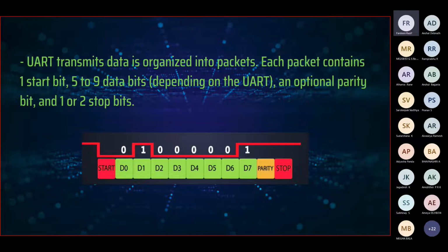So by that logic, each data bit will take 1 divided by the baud rate. That was what I was hoping for. So initially the data line goes from high to low, to show that the data transmission has begun.